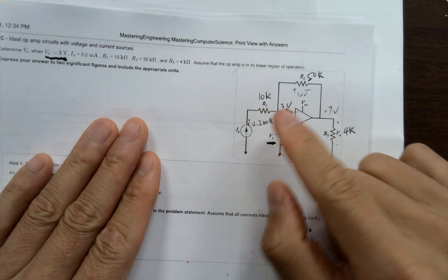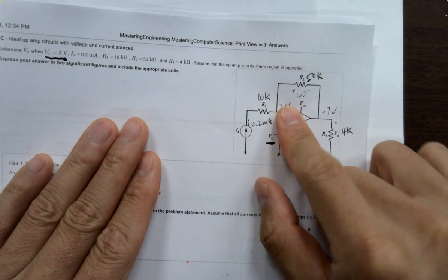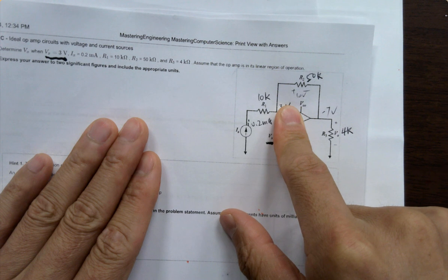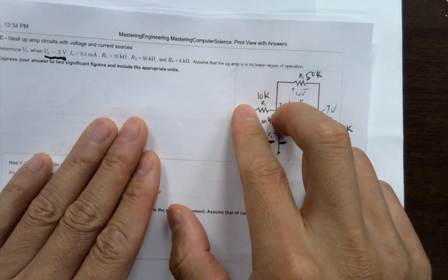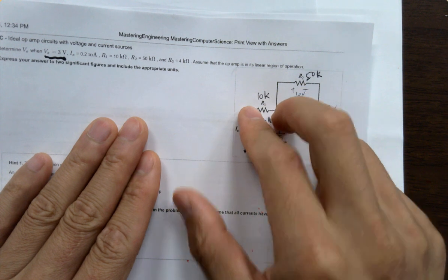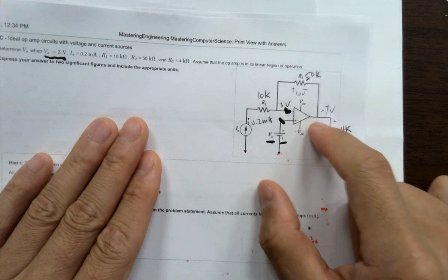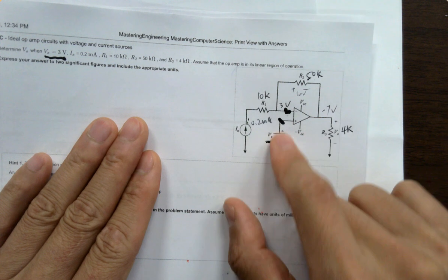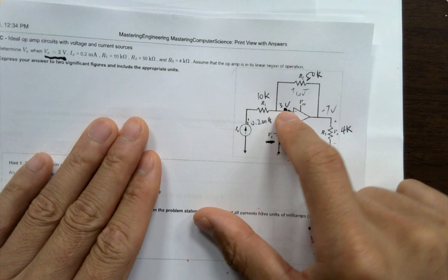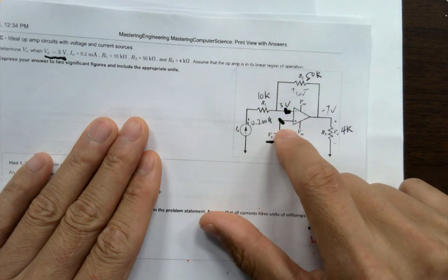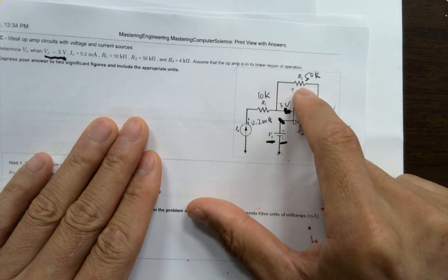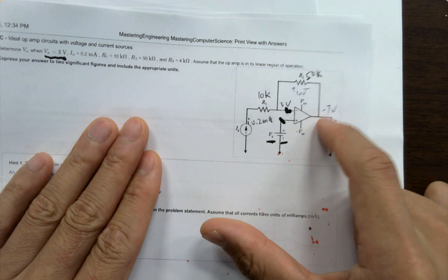One quick question: if you just know the current without knowing the voltage here, can you still calculate everything? Current flows through the resistor, you know the drop, but since there's no reference, you don't know exactly what the value is over here. If the voltage here is given and you get a current, find the drop here. Since this is given as 3 volts, dropped by whatever here, you can get VL easily.